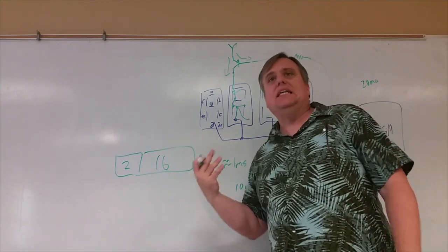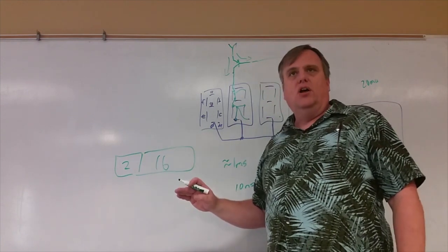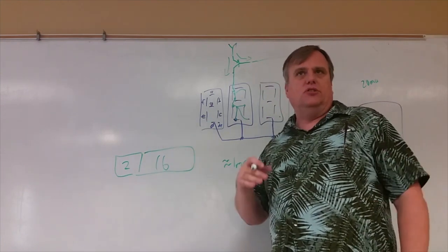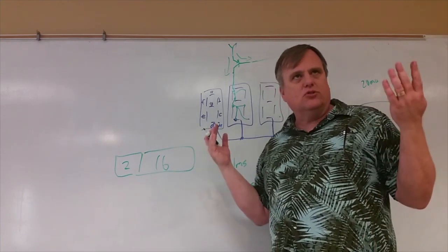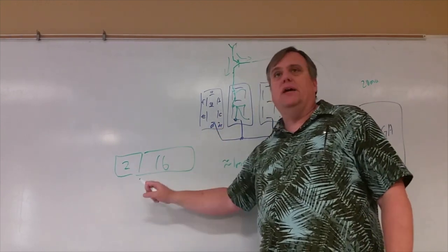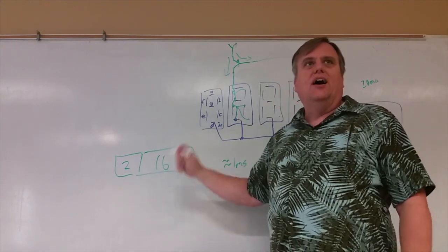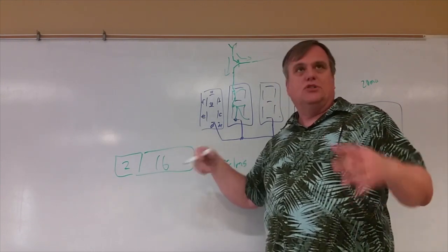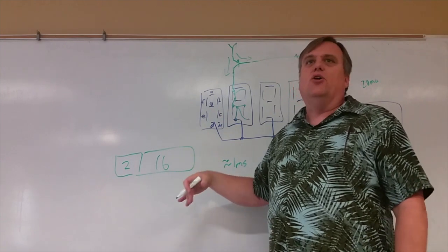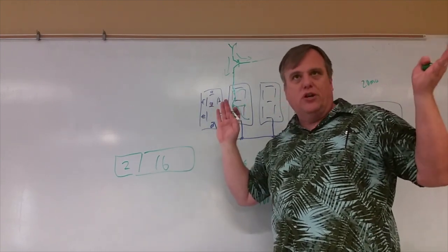If you really need it that precise, that I don't want 64,000, I want 50,000 instead for the recount, then I'd have to have a separate 2 bits. And I'd have to have my 16 bits, which is my 64K, and I'd have to look to see when this is equal to 50,000 or whatever number you're looking at.